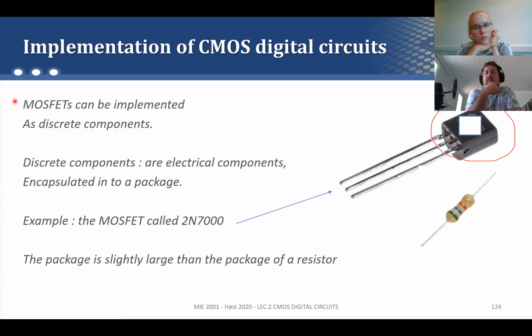But this is mainly one thing in analog electronics. And this connection is done inside of this package. That's why you don't see the bulk, because the bulk is actually connected to the source here, and you don't need to connect it to anything else. So theoretically, Luca, this is a PMOS then? No, this is still an NMOS. Ah, NMOS, okay. Yeah, but there is no bulk terminal because it's connected to the source.